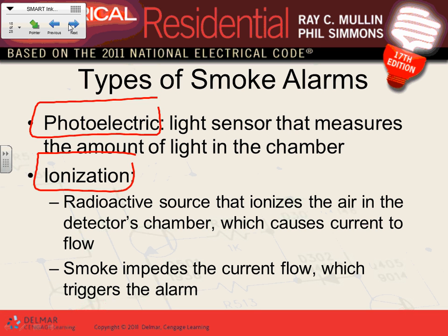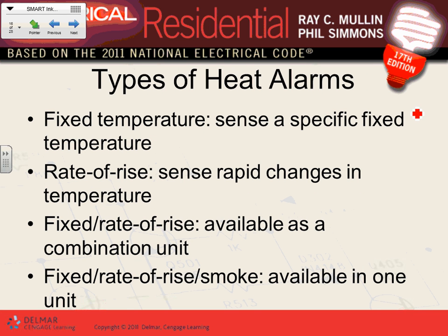Can I have a thumbs up, Chad? We will talk about these technologies more as we go into the full fire alarm system in the commercial project too. So either way, smoke impedes the flow of the current or blocks the beam going to the sensing mechanism of the photo detector when the smoke gets into it. Okay, so that's basically the two technologies that they have.